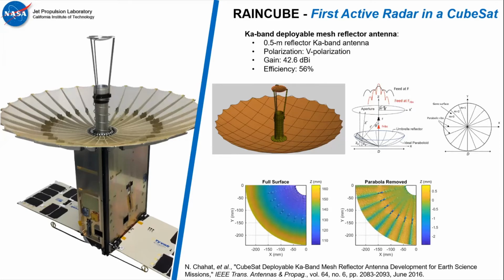So this is what we did, and we compensated the loss close to almost 0 dB with this number of ribs. So a bad RF engineer would have imposed to the mechanical engineer to increase the number of ribs. And as a result, things would have probably jammed during the deployment. So you need to be aware of this trade-off because that's very important if you want to be successful.